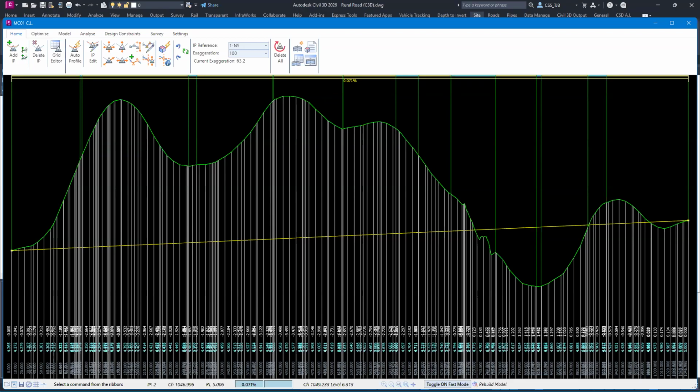The user has the ability to tweak the algorithm in regards to things called mutation and crossover, which is how much it drifts from version 1 to version 2 type stuff. And there are three at the moment, and this is only our first generation of this, three components or elements that you can control, which are things like cut fill depth at the center line, grade, and a generic K value. And you can basically set your desired value, and then you can push the weighting around on the three of those things. So you can say, well, I'm most impressed with wanting to get something to do with maybe grades, not so keen on K values, or not so keen on cut fill depth, or you can turn it off altogether. And then when it completes, it'll give you an overall fitness score on how well it's achieved and whether or not it's had to penalize one of those things because it's had to break one of your required, also not required, your desired settings.